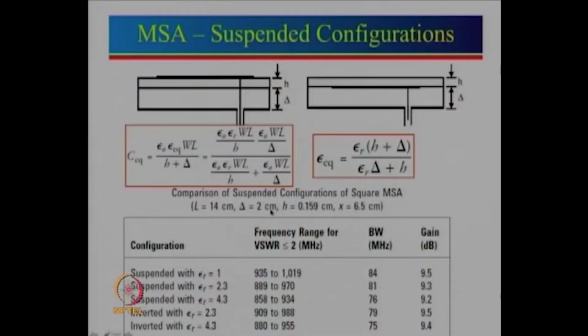So for those kinds of applications, generally one uses a high-cost substrate, but nevertheless cost is always a good thing. So if one can design an antenna with low cost without affecting the performance significantly, and we did notice that the gain just reduces slightly by about 0.1 to 0.2 dB. So in fact this is a very good way to design an antenna by using this here.